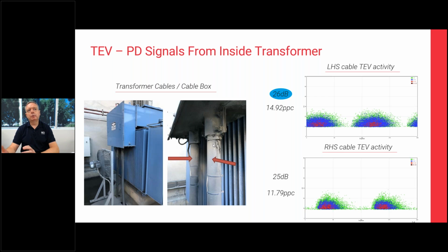So at that time, we take an oil sample from this distribution transformer. That oil sample also indicated high levels of acetylene, so we've got partial discharge going on inside of that. So the actual maintenance activity, in this particular instance, is to replace that transformer. For this particular site, given the cost of the transformer and the criticality against the process, the easiest way to do it during that shutdown was to actually replace that transformer.